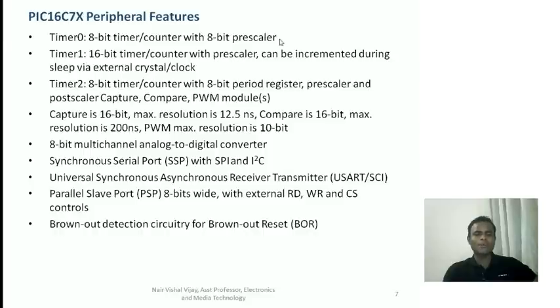Now that differs for each timer: timer 0, timer 1 and timer 2. As you see, in timer 1 also you have a prescaler, but it's a 16-bit timer, and it can be incremented also during sleep mode. So timer 1 can be used even for real-time clocks, as you know, your system clock or real-time clock. Even when the computer sleeps or is shut down, it is running.